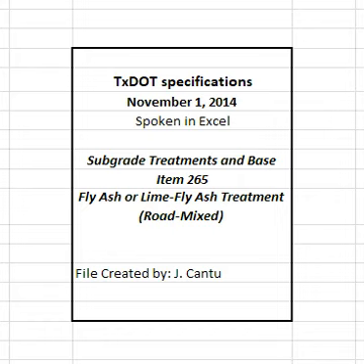When dry quicklime is applied as slurry, use 80% of the amount shown on the plans. Distribute slurry uniformly by making successive passes over a measured section of roadway until the specified lime content is reached. Uniformly spread the residue from quicklime slurry over the length of the roadway being processed unless otherwise directed.